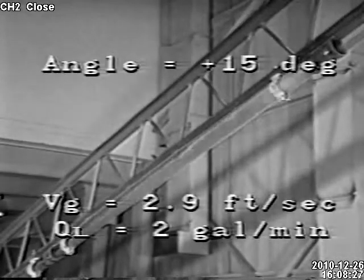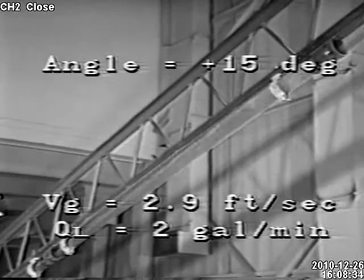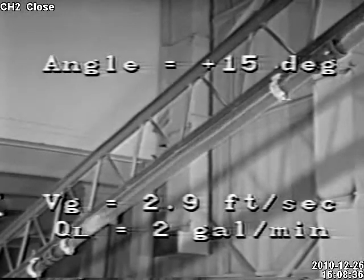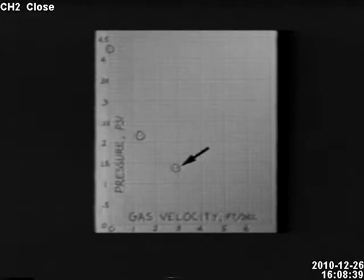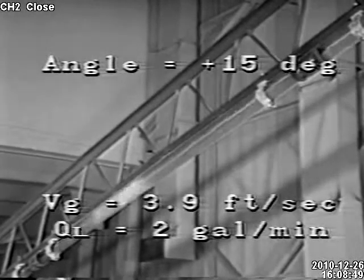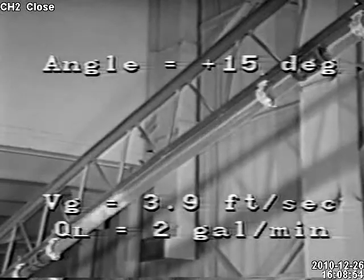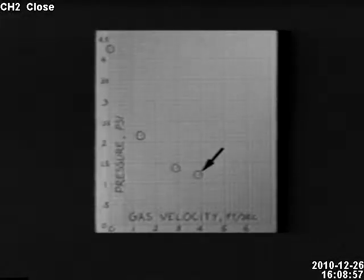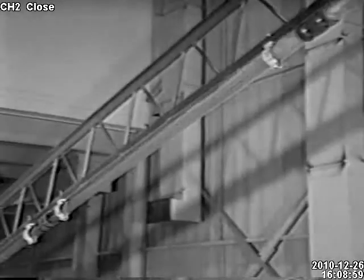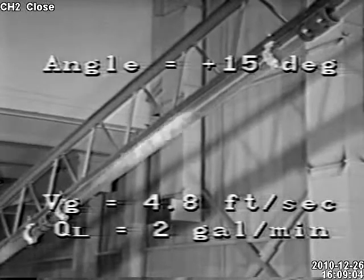With a slightly higher gas rate, the new flow conditions are as follows. And the pressure drop continues to fall to 1.4 psi. At 3.9 feet per second, the pressure drop reaches a near minimum of 1.2 psi. And at 4.8 feet per second and beyond, pressure drop increases with further gas flow.